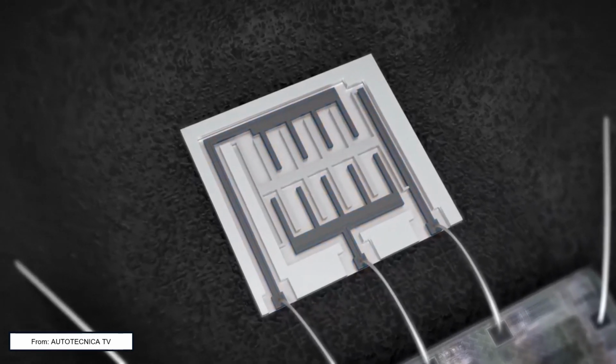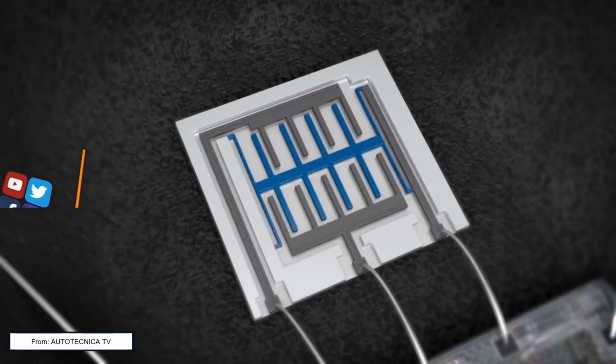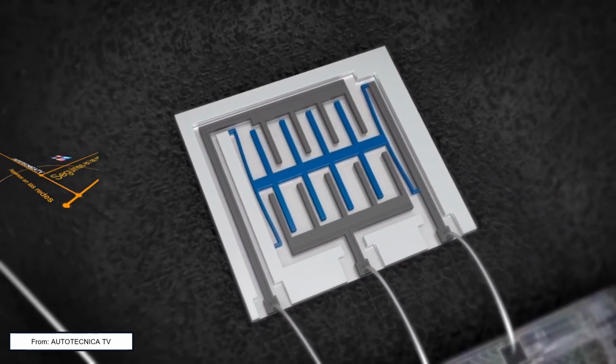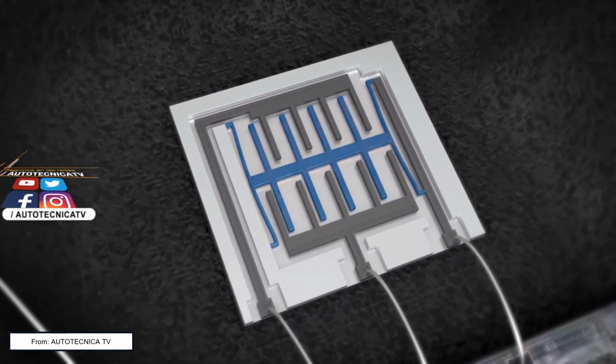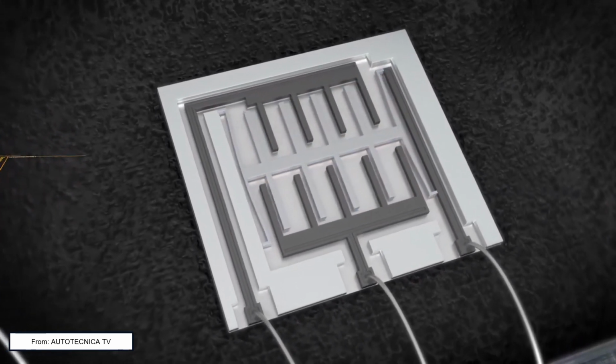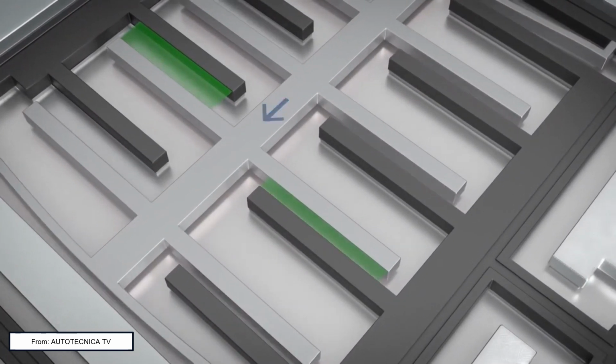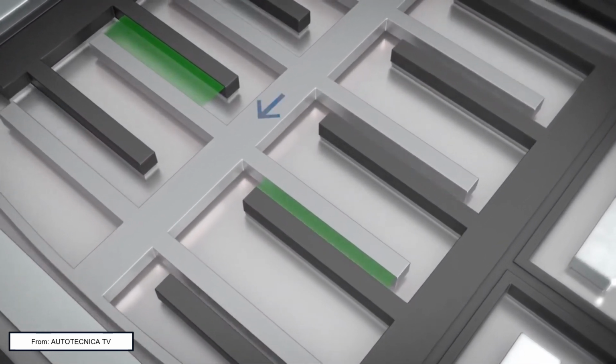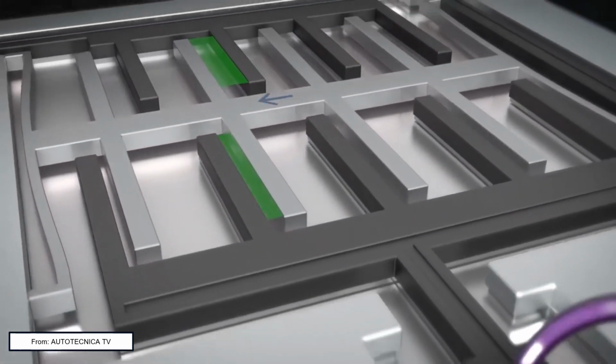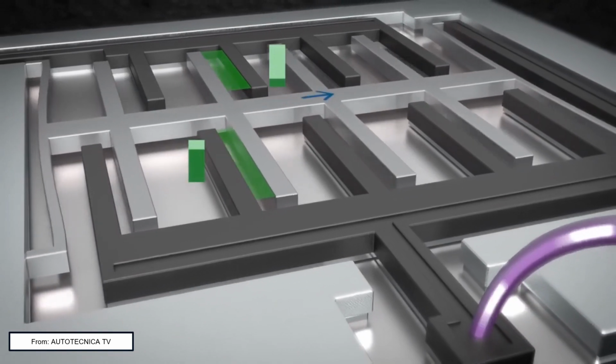Capacitive accelerometers on the inside have a moving mass and a static mass. When acceleration is applied, the moving mass moves away from the static mass that is electrically charged. The separation makes the capacitance vary, generating an electrical signal proportional to the acceleration. These sensors are commonly used in portable devices due to their low energy consumption.